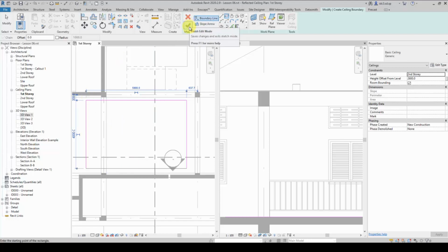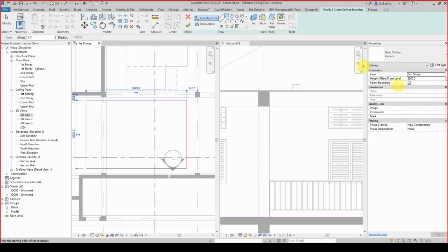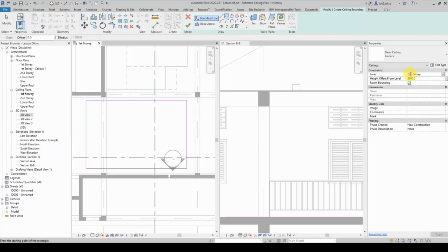So we would not be seeing the beams at this region at least. Now the key issue is, if you look closely, we zoom real close, we will see that the ceiling board itself, the height of the ceiling finish, is actually the same height as the soffit. This is what we call the soffit of the beam itself. So that is the problem.